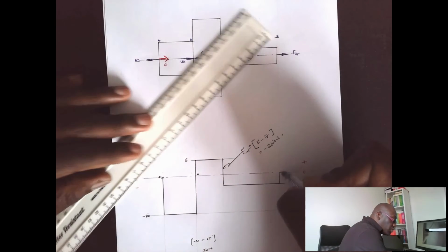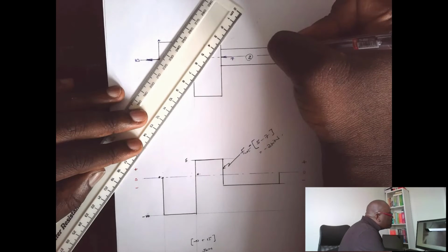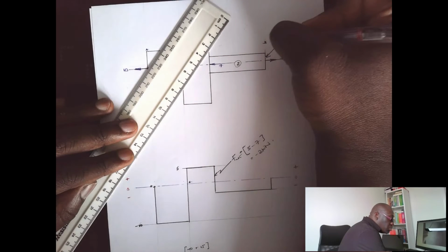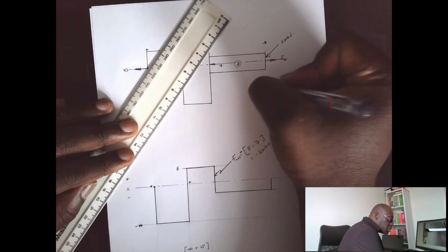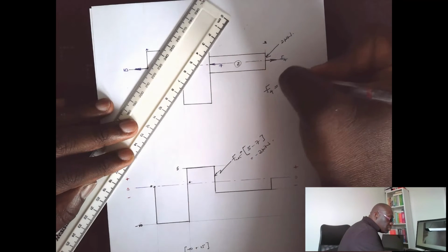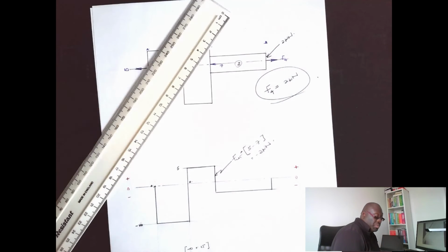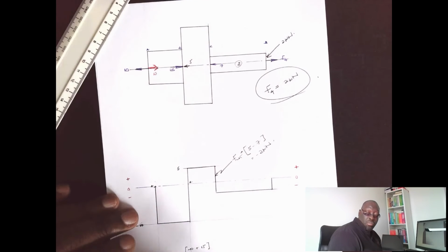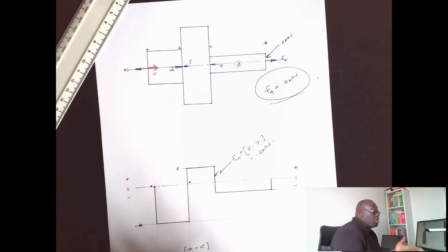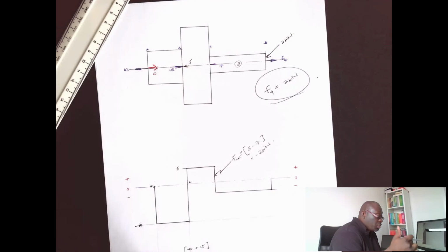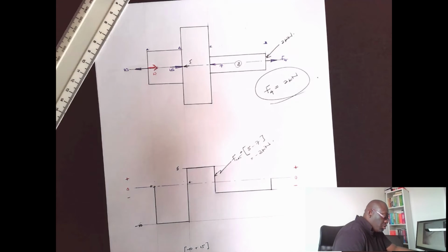So we are assuming that the external force here, in terms of the components, will equate to 2 kilonewtons. So force F4 is 2 kilonewtons. And we can use the equations of equilibrium, as I like to call it, to work out what the balancing forces are to depict what minus F4 is. And if you work it out, you realize that you get a force of 2. So the tensile force that needs to be applied to the component to keep it in equilibrium will be 2 kilonewtons.